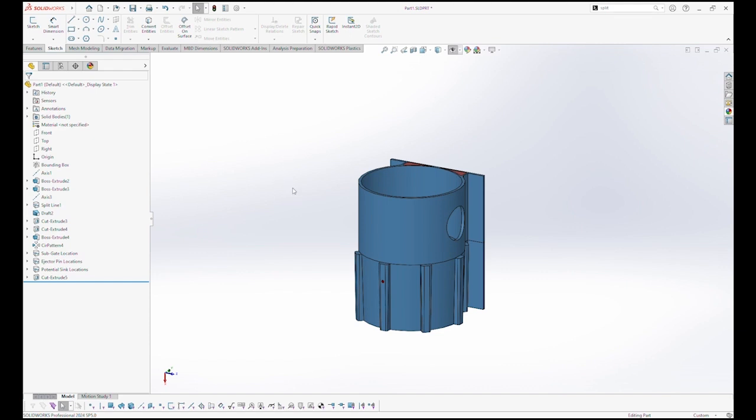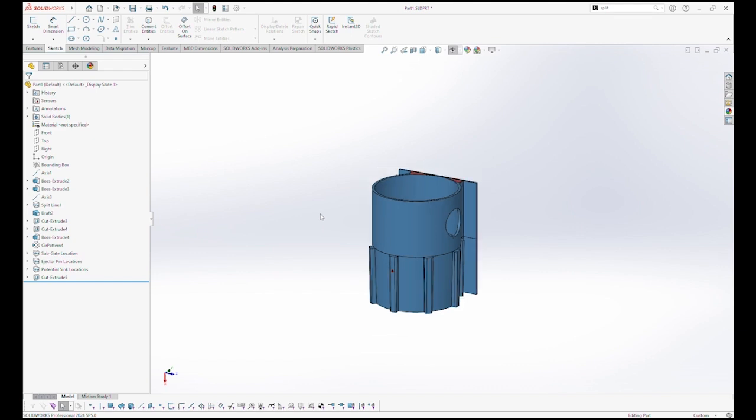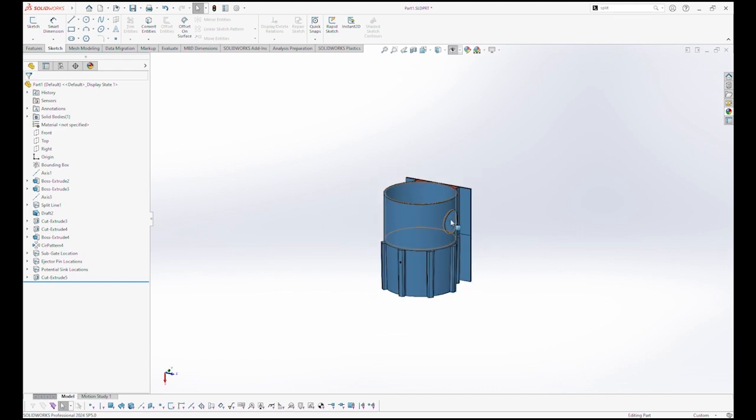It's not impossible to do. It's just you have to know that there's a lot more steel and a lot more machining, a lot more labor involved to do these holes that are perpendicular to the line of draw in a particular part.